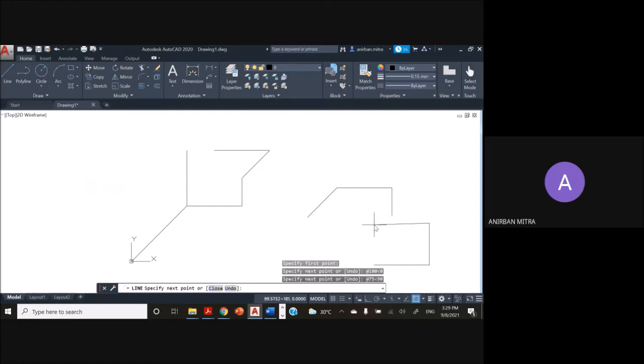You want to now move in the negative x direction. So @ 100, what should be the angle here? 180 degree. That is correct. Now you can move directly down, and with the O snap, you can close this up, or you can draw a line at 270 or minus 90. That closes up the rectangle.